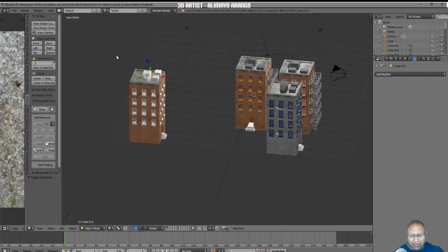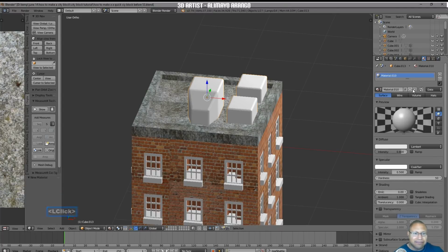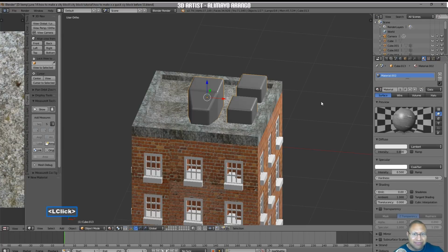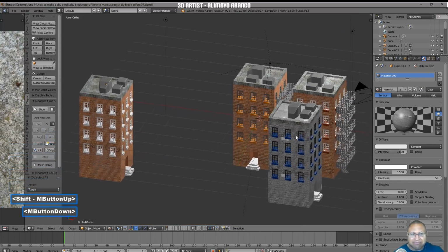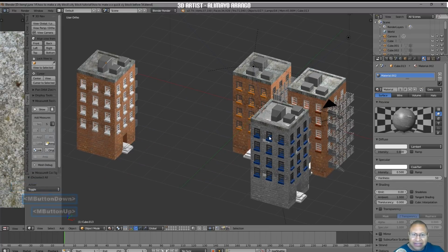Okay, I'm going to hold Shift, then press B in object mode. This makes you zoom in. Select it here. I'm going to go to my material tab, select new. And then I'm going to click here, and then I'm going to select material 2. I'm then going to press A to deselect. Okay, I'm going to roll the mouse wheel to zoom back. I'm going to hold Shift and middle mouse button to pan. I'm getting an angle that I can place the camera to look upon.